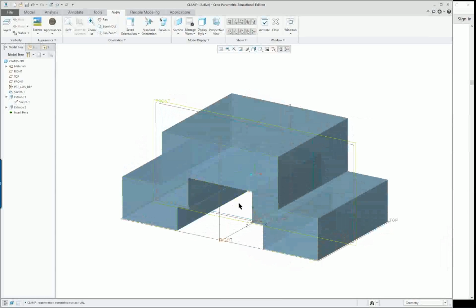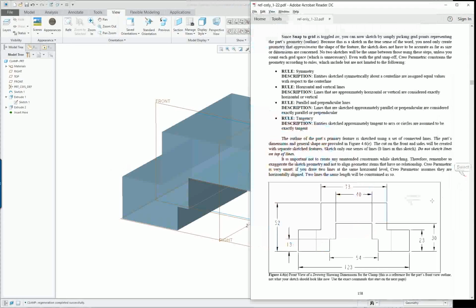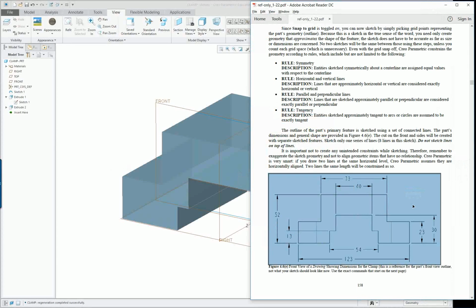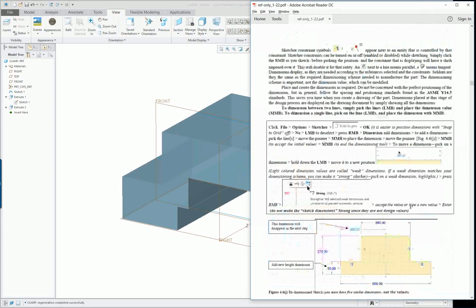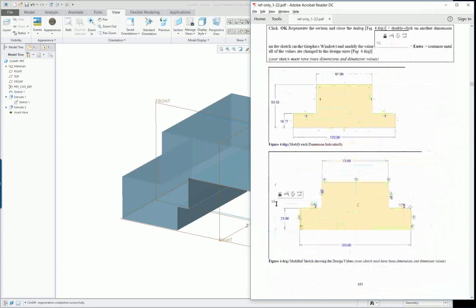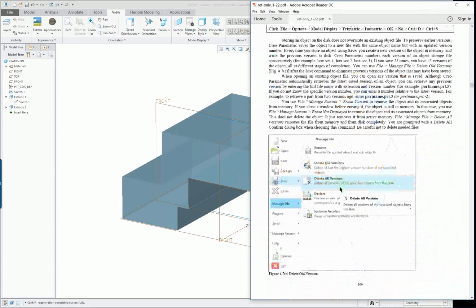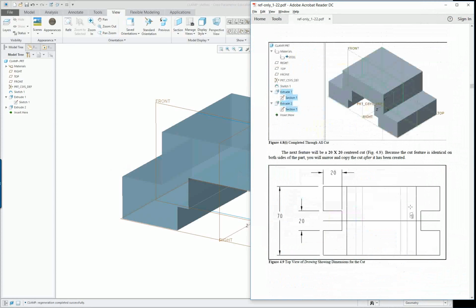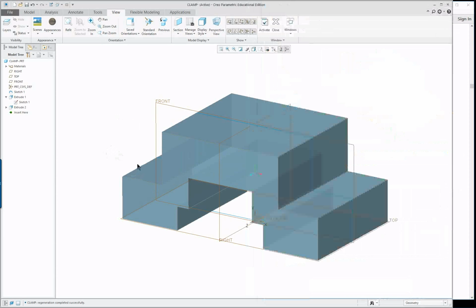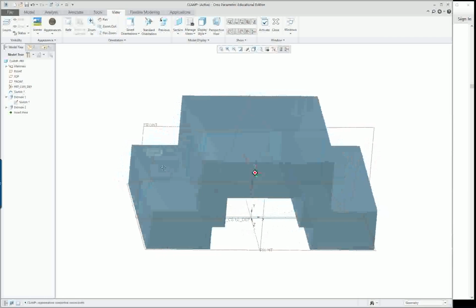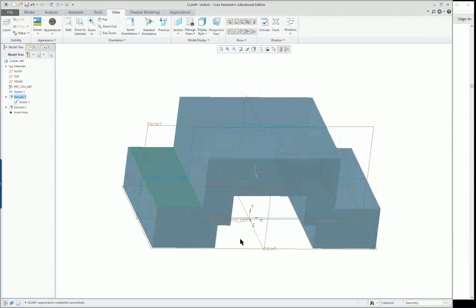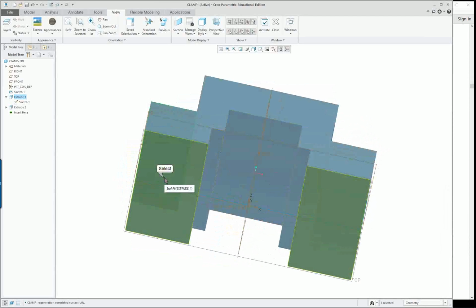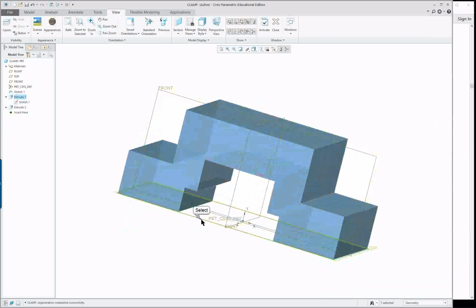Next. This cut done, we're going to do one more cut. This cut is on both sides. See if I go down a little bit, you'll see it. It's a 20 by 20 cut on one side here. So what I want to do is I want to choose, should I sketch on this? Should I sketch on this? Or should I sketch on the datum plane?